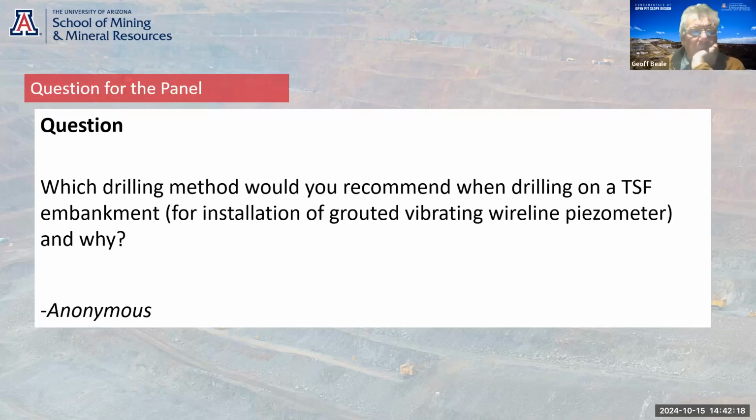You won't. There's a number of ways of doing it. You can put filters in. We've been putting in VWPs, and Jeremy may explain it, but we've been putting in VWPs in leach pads and dump leaches with variable success. But you can again put in lots of lost circulation material to plug up the sides of the holes. But again, you gotta look at if there is any implications of losing a fluid loss in a dam. That's always something to consider.